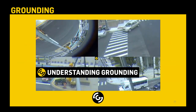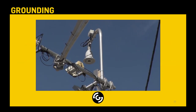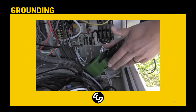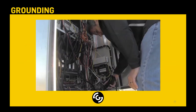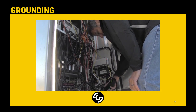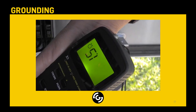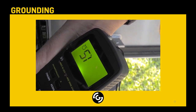Understanding grounding. In this video, we'll discuss the importance of grounding and review the instructions for grounding your GRIDSMART system. A good cabinet earth ground is important for all electronics operating in the cabinet. The NEC recommends 25 ohms or less, and the lower resistance that you can achieve, the better that the equipment will be protected from transients. Additionally, any digital communications will benefit from the reduced noise in the system that will be achieved with a lower ground resistance.